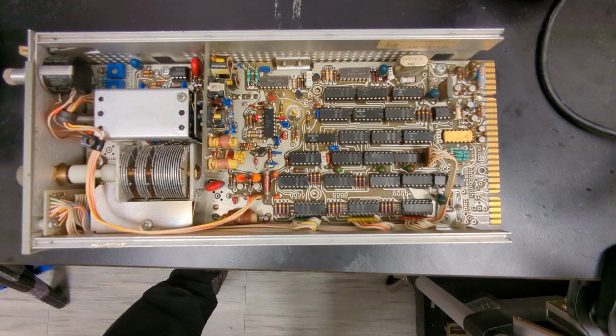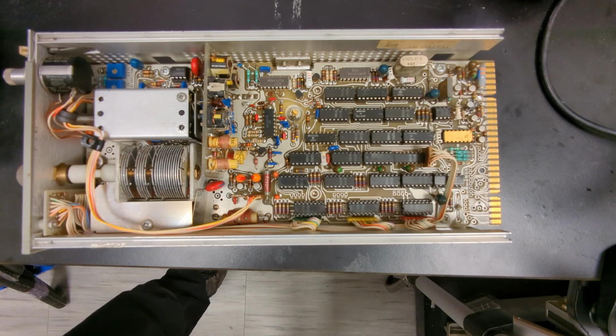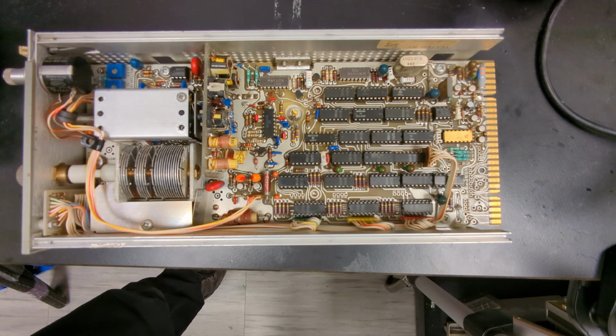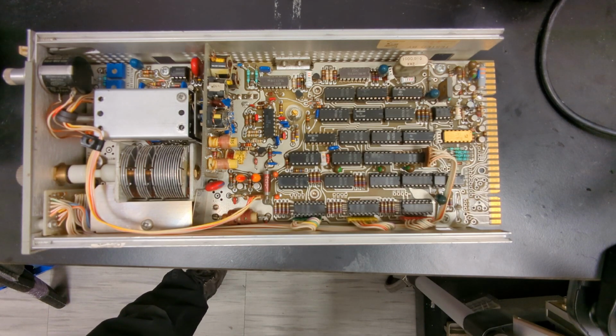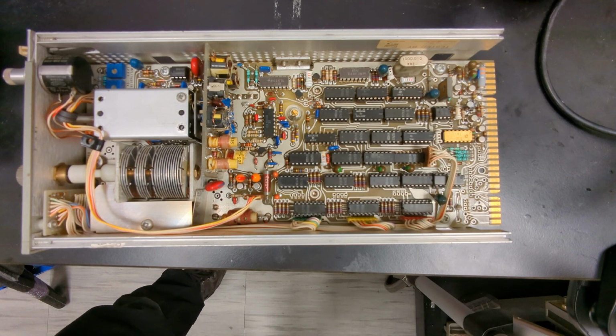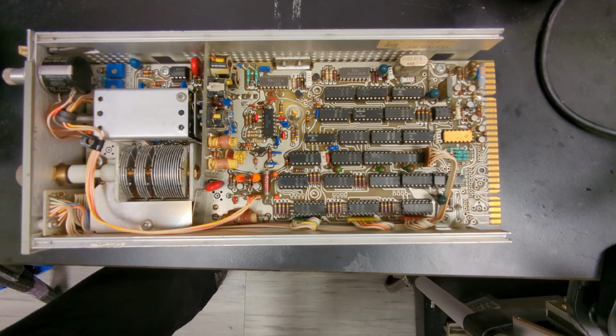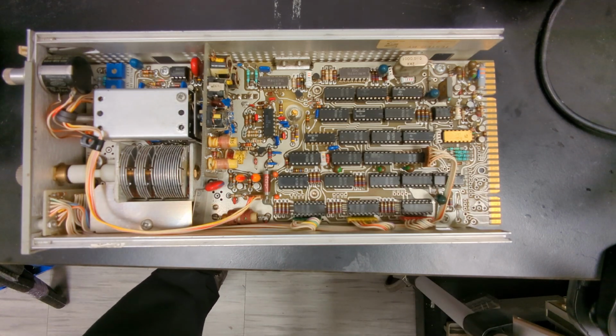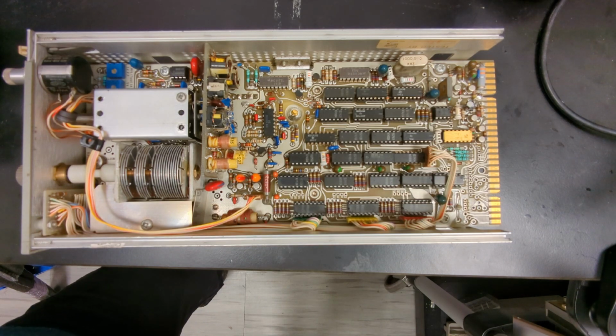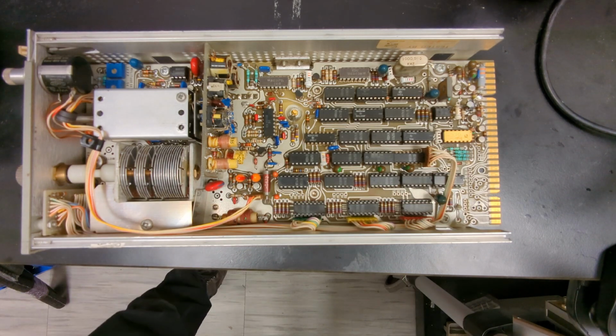So towards the end of the video, we figured it'd be a good idea to look at the power rails, and we found that both rails, the negative 22 volt rail and the positive 5.2 volt rail, were very low. We are running this from a TM5000 series mainframe, not the 500.